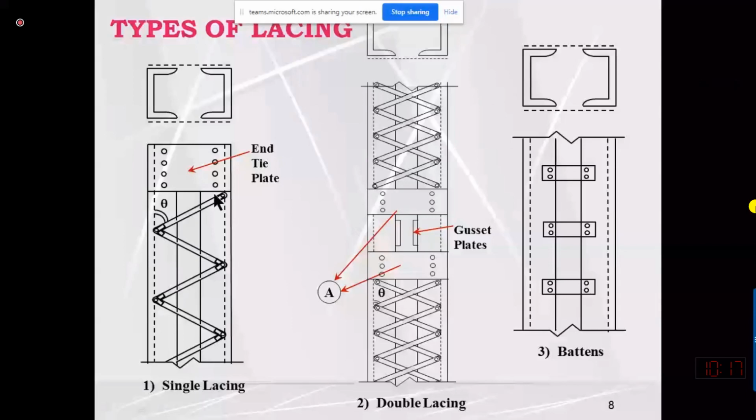This dash line, if I cut the cross section, represents this flat thin steel bar. Actually, the area of this steel bar is very small, so we just represent it as a dash line, and we ignore it in order to compute the gross area. We will see what the gross area is also today.